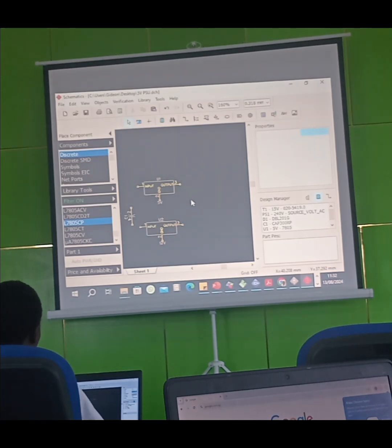If you check the datasheet, you will see that if you want 3.3 volts output, these are the resistor and capacitor or inductor values you should put, maybe 3.3 volts, 5 volts, 4.9 volts, 4.7 volts or 9 volts. You can even make use of a POT for the adjustable one, whereby when you rotate the POT, you have different voltage outputs.